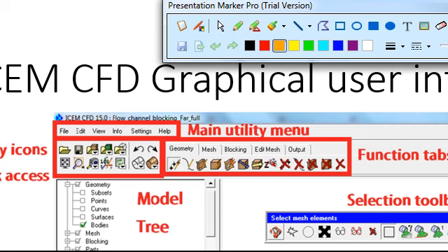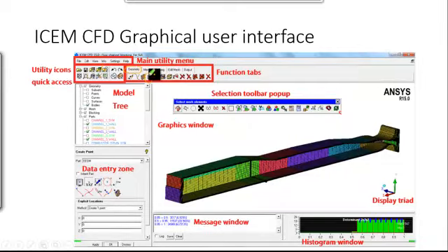Now, how can you define in which section of the geometry you need a volume mesh? For this, you define it with the help of the body, or the material point. The point of the body material is where you define the region that should be closed with the help of the surfaces. There should be no gap between one closed body's surfaces and the other surfaces. Then you define the point, and now ICEM will mark this as a volume for the mesh.